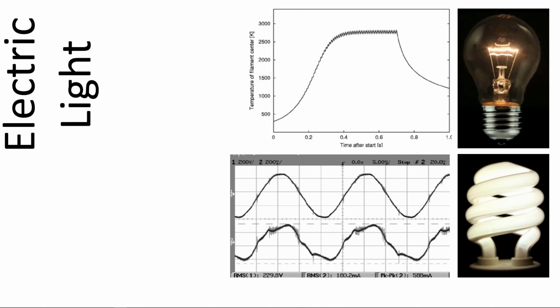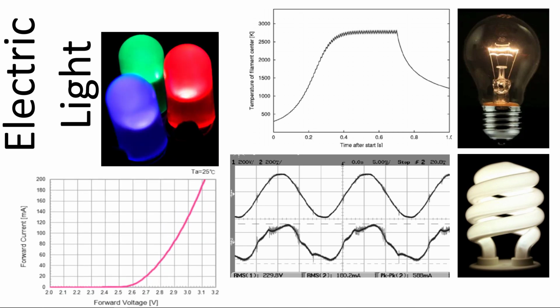If you're doing visual inspection systems, meaning you're using a digital camera to inspect a product and you're using fluorescent lighting, you have to use a special high frequency ballast so the camera doesn't pick up those different ranges of lighting. Fluorescent has its challenges. Incandescent has its challenges. Now LED lighting.